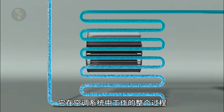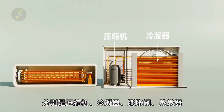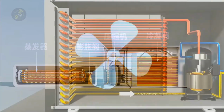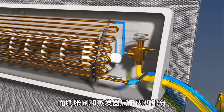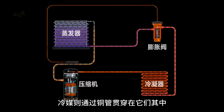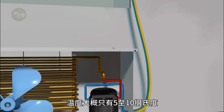Now let's look at the entire process of how it works in an air conditioning system. The air conditioner mainly has 4 core components: the compressor, condenser, expansion valve, and evaporator. The compressor and condenser are part of the outdoor unit, while the expansion valve and evaporator are part of the indoor unit, with the refrigerant running through them via copper pipes. The refrigerant starts as a low-pressure gas with a temperature of about 5 to 10 degrees Celsius.